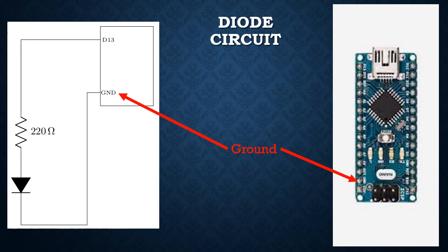The ground pin that's marked here is the one that's on the left side of the Nano when you have the connector at the top. The other ground pin is on the other side of the Nano. The D13 pin is also on the left side. It's the topmost pin. Okay, so you need to find those 2 pins, and then the holes that are in the breadboard just to the left of these 2 pins are places that you can connect wires, and then you'll be connecting that pin to other things.